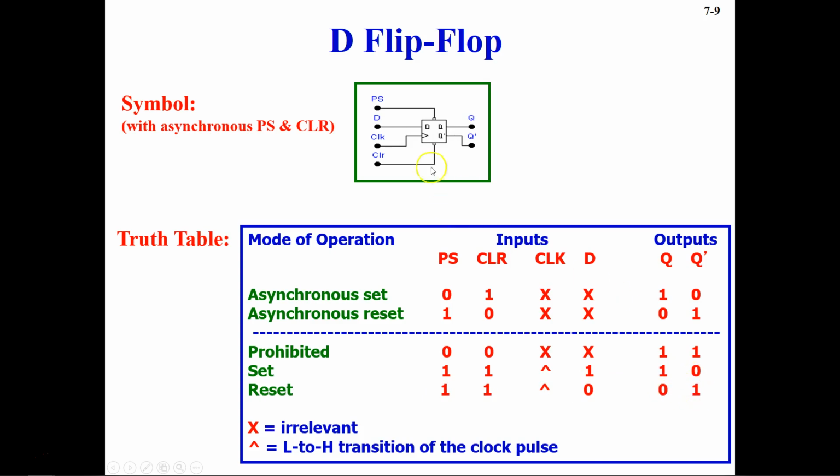If you notice here in the clock input of this IC symbol, you see this triangle shape. This basically represents edge triggering, so you can say that this flip-flop is edge triggered. It is also written here that this is the positive clock, which means the transition of the clock is going from low to high.